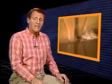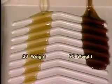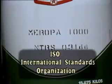There are several different viscosity grading systems in use today. The SAE system, developed by the Society of Automotive Engineers, indicates oil viscosities with numbers referred to as weights. The higher the weight, the thicker the oil, and the higher the viscosity. In some cases, lubricating oils for industrial equipment are classified using the ISO viscosity grading system. ISO stands for International Standards Organization. As with the SAE system, the higher the ISO number, the higher the viscosity.